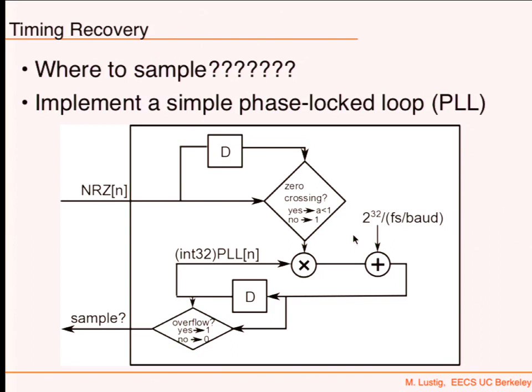You could reset it to 0, right? And that's going to be a trade-off, but this, remember, is noisy. So if I reset to 0, then it's completely going to lock to this, also to the noise. So it's always a balance of sensitivity to noise. You know that the sampling rate is every 40 samples at 48 kilohertz, but sometimes you don't know where it starts, and so you want to be able to sync. If I just nudge it, it's still going to have a certain rate that fits. On average, it's not going to move. It's kind of like filtering.